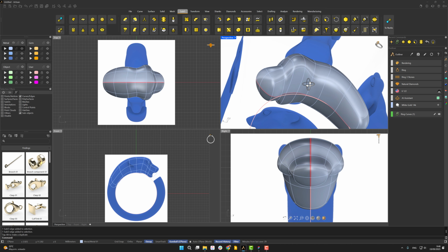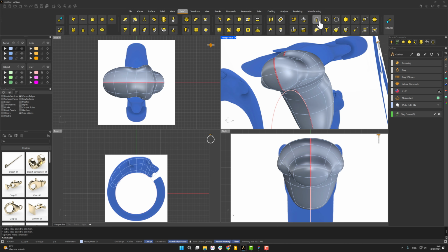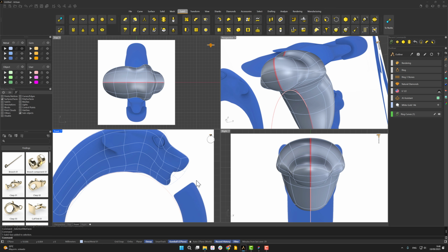For the mouth area, we need one more edge loop. For that, select the entire horizontal loop and then use the Insert Edge command to add another loop in the lower part. Now from the front view position, adjust them to the mouth.